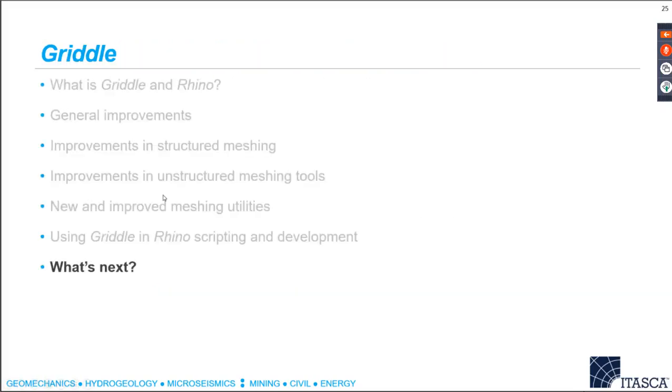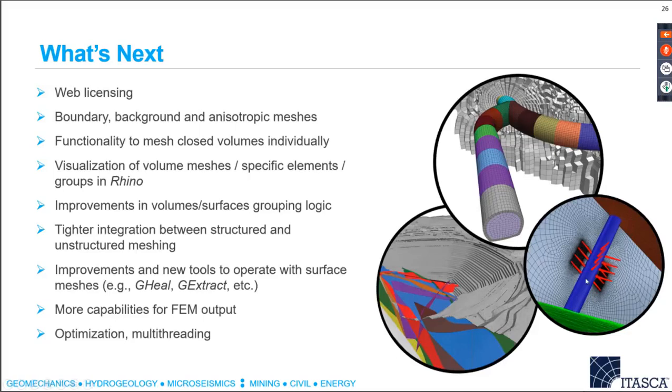Actually, here's an example of a well bore with perforations that was automatically created by, well, it wasn't a Python script, it was C++ code. But it just started from a set of numerical parameters that specify, for example, well bore diameter, perforations diameter, location of different faults, and so on. Initially, there was no model or anything, just a few numerical parameters. And the code automatically created this type of model and meshed it and produced a volume mesh.